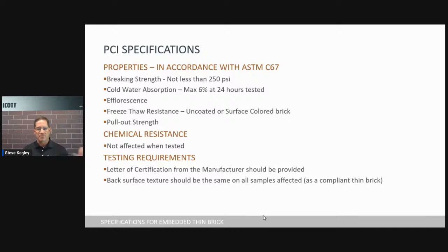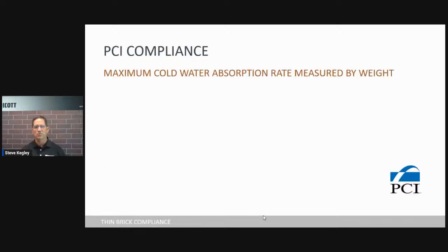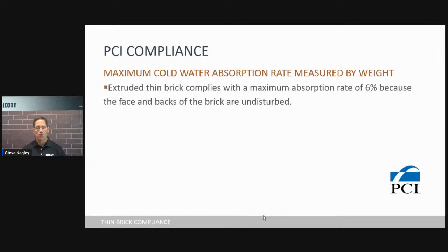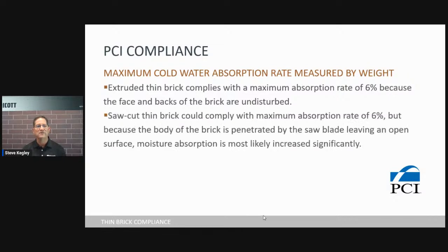And again, the back surface texture should be the same on all the samples that are used when they're doing the testing. And you'll see some testing that we've done that I thought I'd throw in here for you to understand. That maximum cold water absorption rate is measured by weight. And when I mentioned to you that a face brick is an extruded brick, just like an extruded thin brick is, except they saw the face off of it and disrupt the makeup of the brick when they're making thin brick out of it. We do samples in the industry every day, just exactly like that, but they're just samples. They're just going on a sample board, okay?